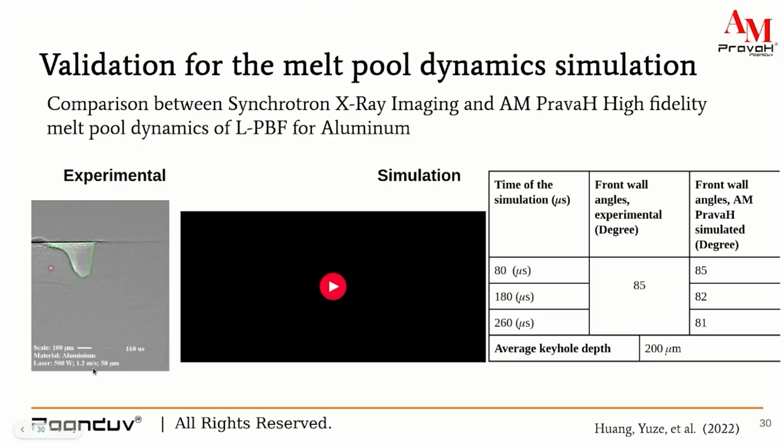The further quantification can happen with respect to what is the contact angle between the substrate and the bead formation. So when the laser power is varied from 1200 watt to 1800 watt, we have compared the contact angles with experimental data, and we can say with surety that these are in good agreement with the experimental data that we have achieved.